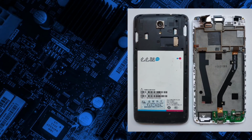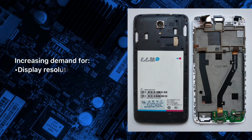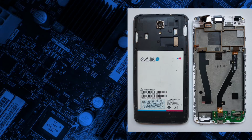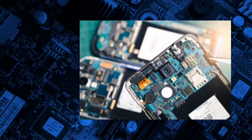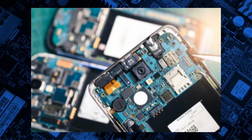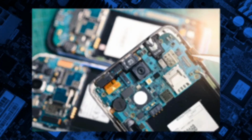Smartphone and mobile influenced display technology is evolving rapidly to cover the different use models associated with generating and consuming content. This has led to an ever-increasing demand for display resolutions, refresh rates, compression technologies, and gesture control technologies. One of the advantages of C-PHY technology is that it enables higher resolutions while keeping link data rates relatively low, and this helps avoid electromagnetic interference with the modem and other radio components on the phone. C-PHY signaling also has beneficial spectral properties that help it coexist more easily with 5G components on the same hardware.